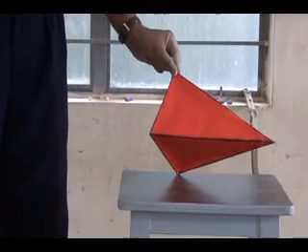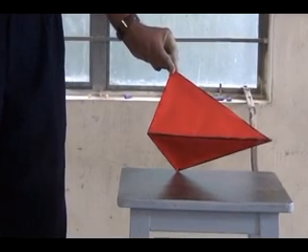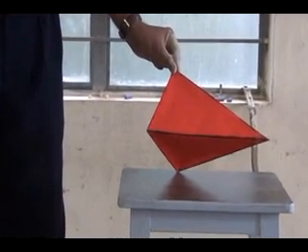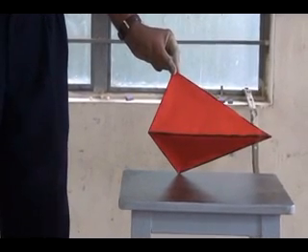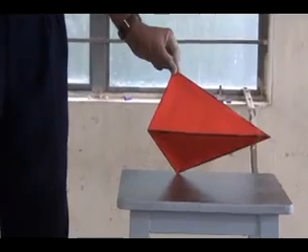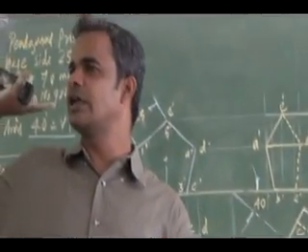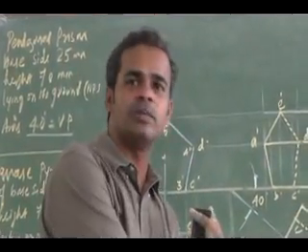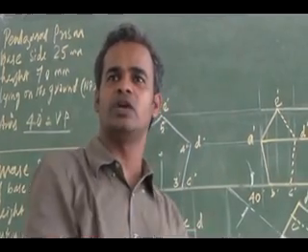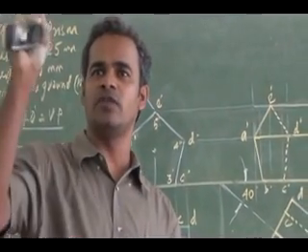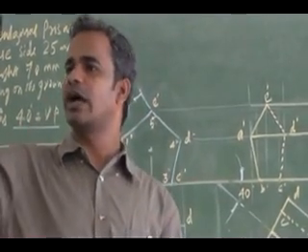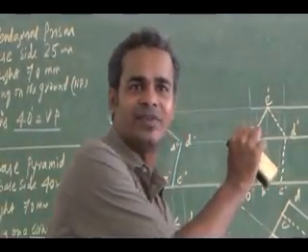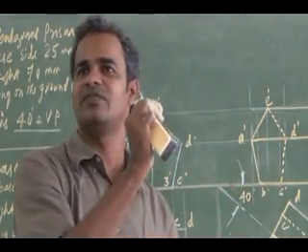For this you have to draw the true shape, and so for this you have to draw the front view and top view. So in an easy manner, without understanding, where I have to draw the base straight away: the axis is inclined to VP, so straight away I can draw the base on VP. While drawing the base square on VP, how do I have to draw it? That orientation is given. So a corner should touch the reference line.